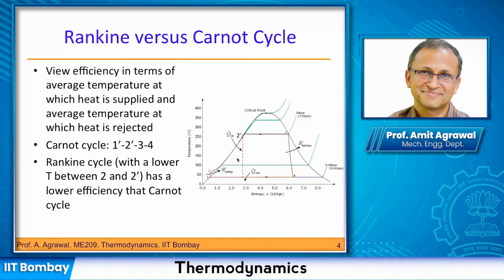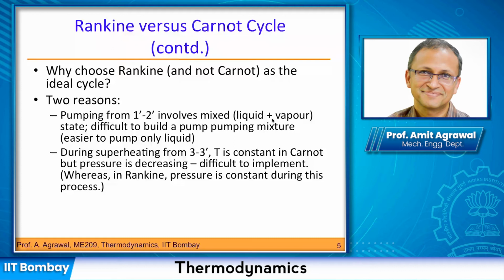And when we go to a turbine, we see that if you have liquid droplets in a vapor, then the droplets, because of their own inertia, can move around very fast, and they can impinge on the surfaces, and they can create erosion of the surface of the vessel in which things are contained. So that's where the difficulty lies. It's not just liquid or just vapor, it's that when you have a combination, you have difficulty.